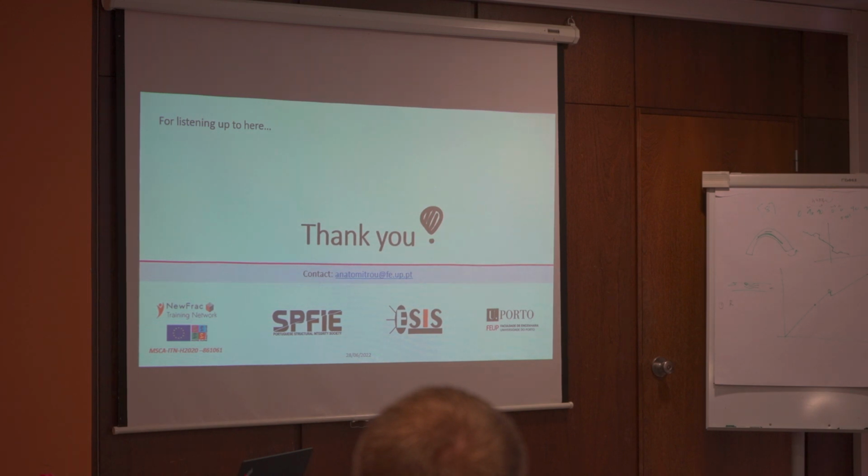So I assign orientation to the material. So here where I use the principal axes, it's just XY. And those are my principal axes, and everything else runs internally in the equation. Okay, I see. So the laminate is represented just with one layer. It's represented by the equivalent stiffness and the equivalent toughness based on the equations from Reinoso. Okay, I see. So that's the idea that we want to try to follow in the on-axis cases that we should know.